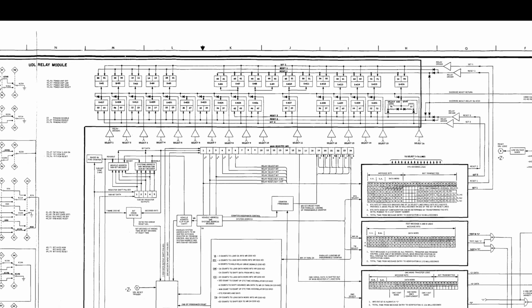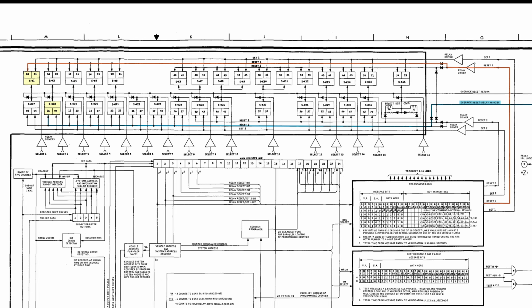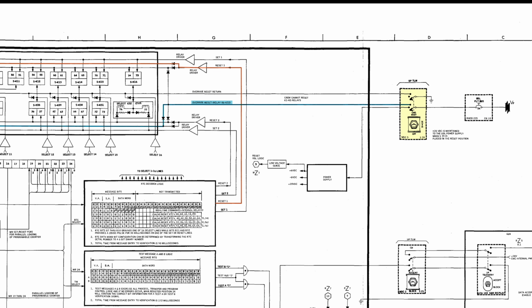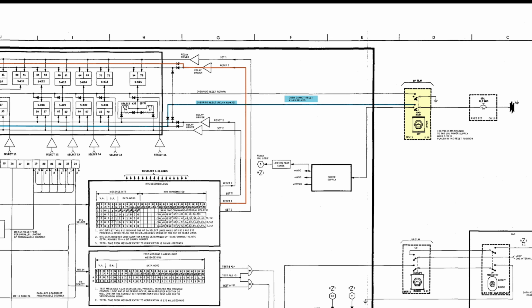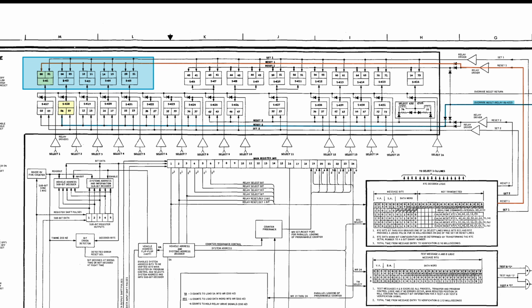You can actually double check that in the UDL schematics. Here is the abort A SK1 relay, and it can be reset from the ground via this wire. But it has no reset connection to the front panel. The abort B relay does have such a connection, called reset override, leading to the up telemetry command reset button, and is pointed out in this side note that says crew cannot reset K1 to K5 relays. Which are these relays over here? The side legend tells us what they do.